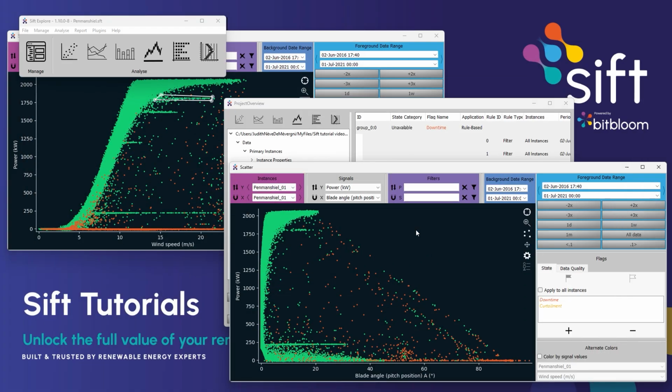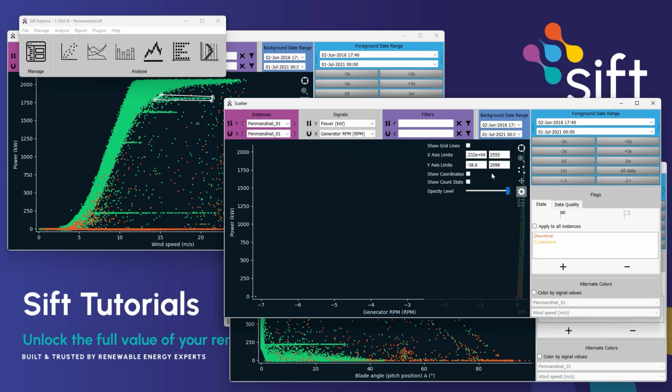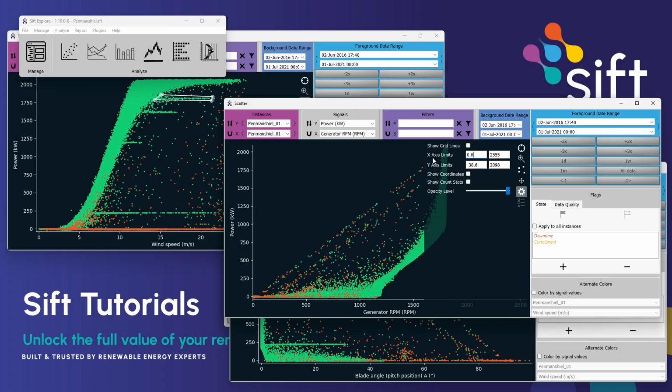As the wind picks up, generator speed increases. When generator speed reaches a certain value called the cut-in generator speed, the turbine starts being able to produce power. We will use the cut-in generator speed at this turbine to differentiate idling and curtailment. This value is easily identifiable from the power versus generator speed plot. To do this, let's zoom into the X value where we see Y values start to increase.